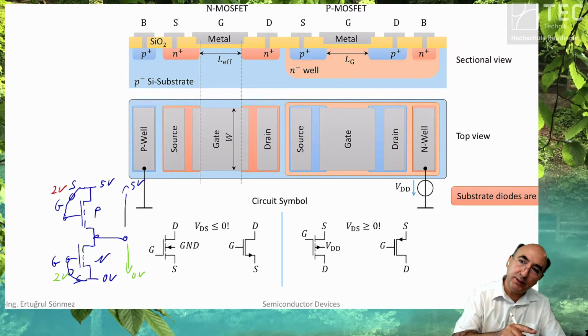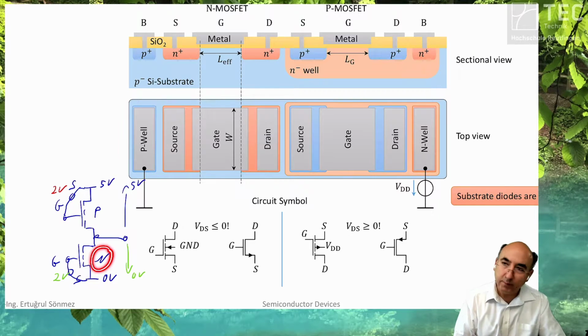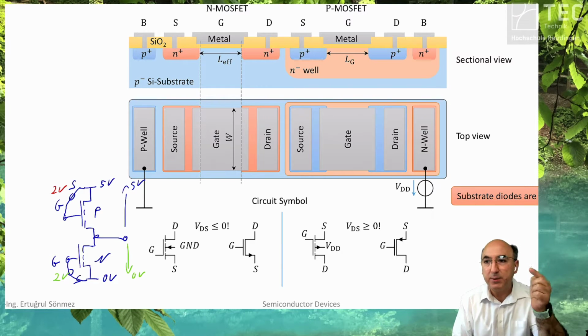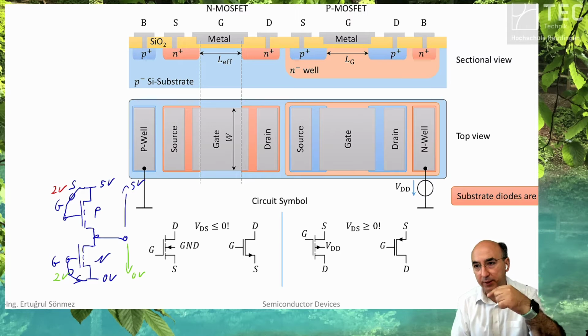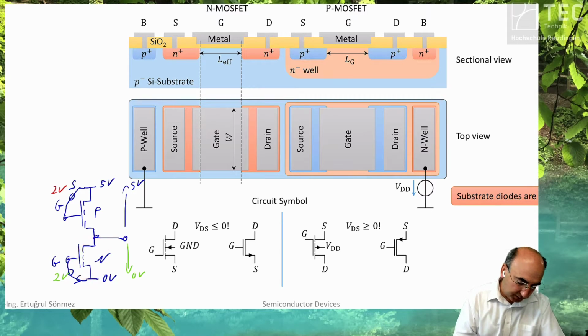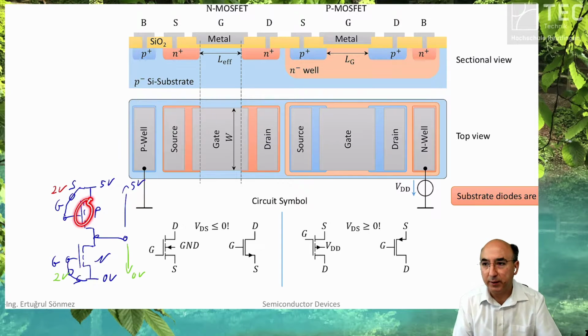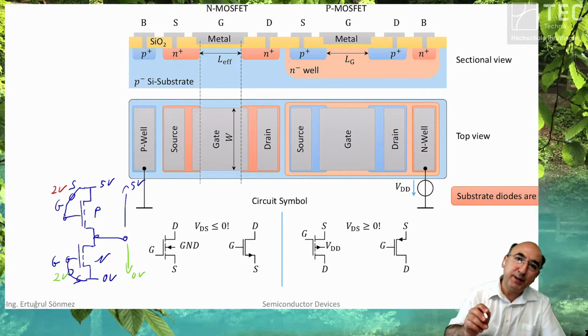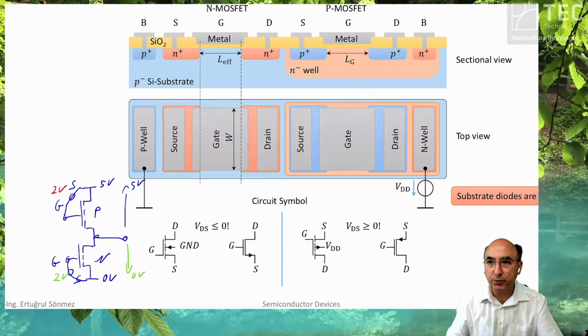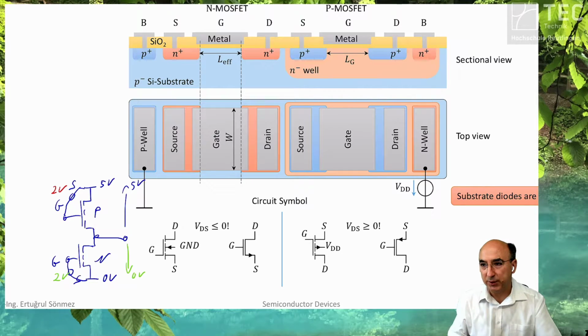This is not the case in bipolar transistors. The N-type bipolar transistor, it is an NPN, we haven't learned it, but it will come, is very fast, it's great, you can make gigahertz circuits, but the PNP bipolar transistor is very slow. It's not usable in the same frequency range. Not even in the vicinity of the same frequency range.